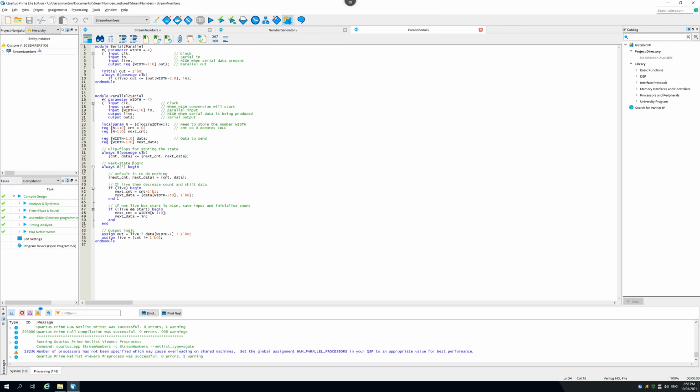Because it's inside a begin-end block, we're doing behavioral Verilog in here. If I were to overwrite any of these values, then just like in a C program, it's the final value that will be the true answer. Because this is behavioral Verilog, it's describing the function that computes what we want. It's not describing directly the hardware at all. So between begin and end, think of it like a C program. But be careful of that.